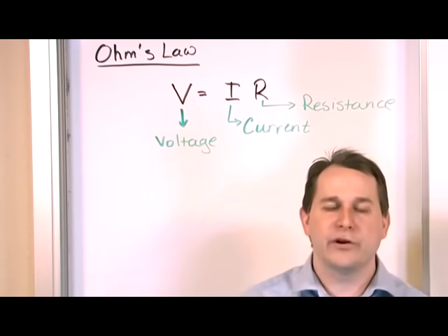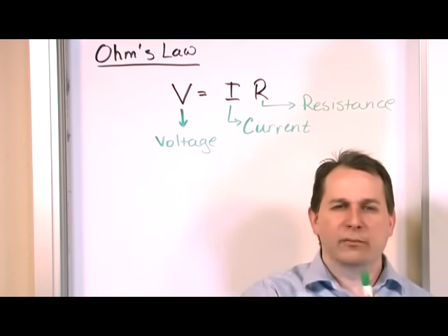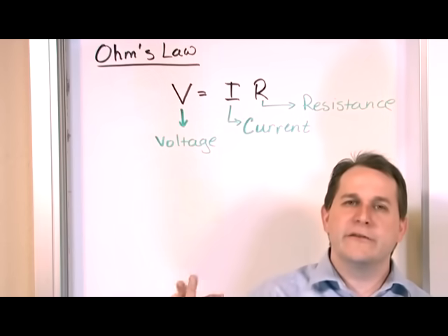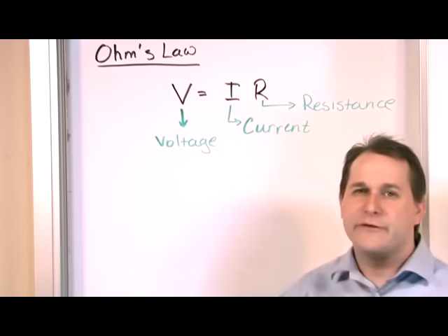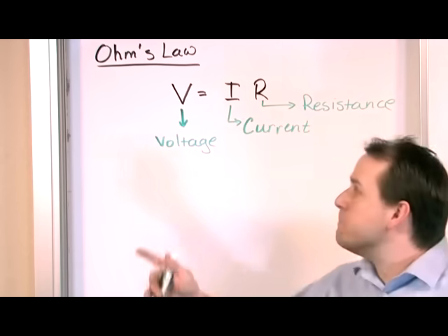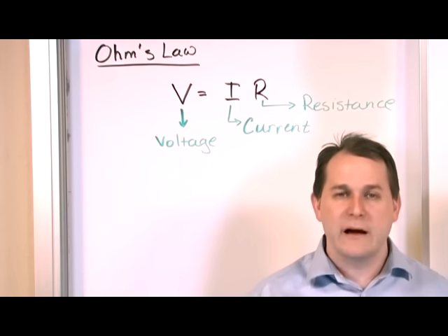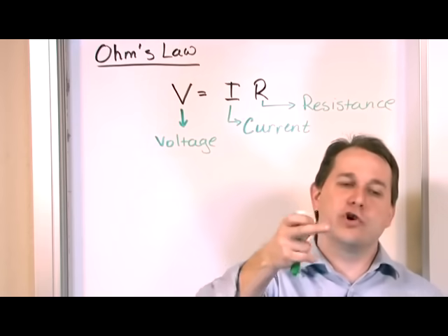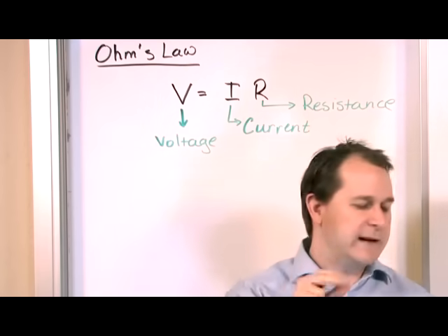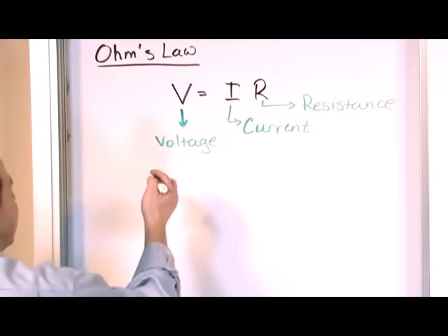But in our study of circuits, we're going to begin by talking about resistors, resistive networks. So think about some resistors over there. So the current is going to be going through those resistances. So whatever the current is that's flowing through a resistor, multiplied times the resistance value itself in ohms, is going to tell you what the voltage drop, what the voltage is across that resistor, right? So let's talk about it in a little more detail, and you'll see it with some pictures as well.